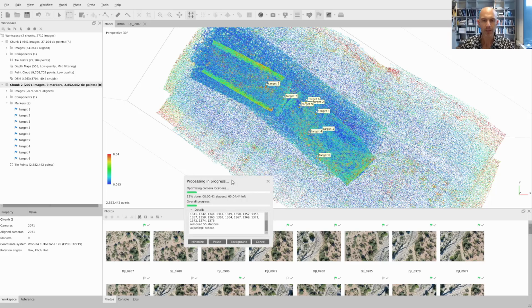What you can see here is that the high elevation flights that give the overview have a lower point density. You see the SIFT features are much lower than in those areas where we have multiple flights at different heights. There is often a problem with aligning some of those flights. You see that the borders of this upper flight are not very well aligned.